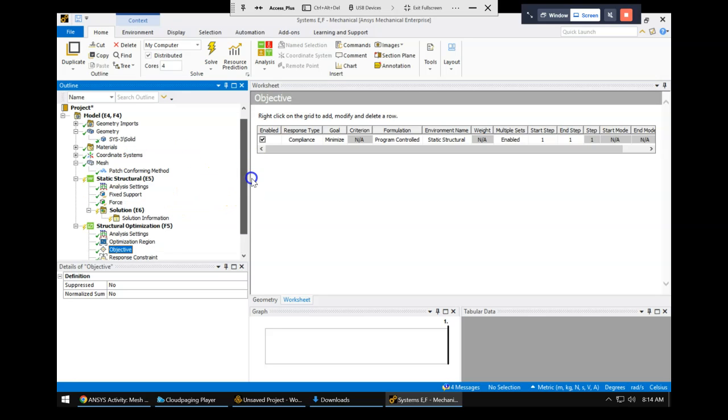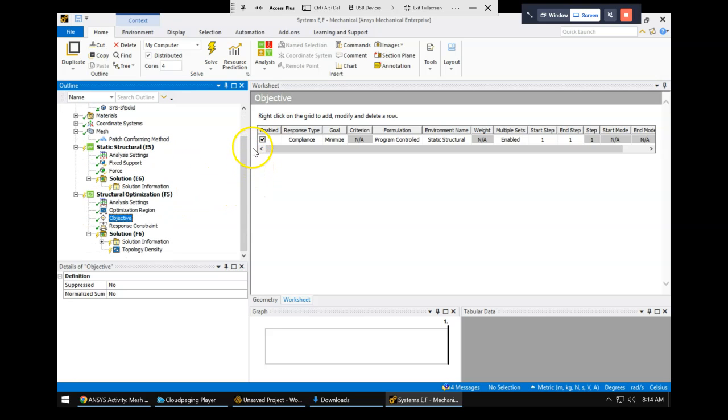What you'll find with shape optimization is there are a lot of ways to get crazy looking results, or results that fail. It says it doesn't converge. So you just have to play around with it and figure out what's going to work for your model if you choose to use this approach for your projects. What I'm going to do is the objective.